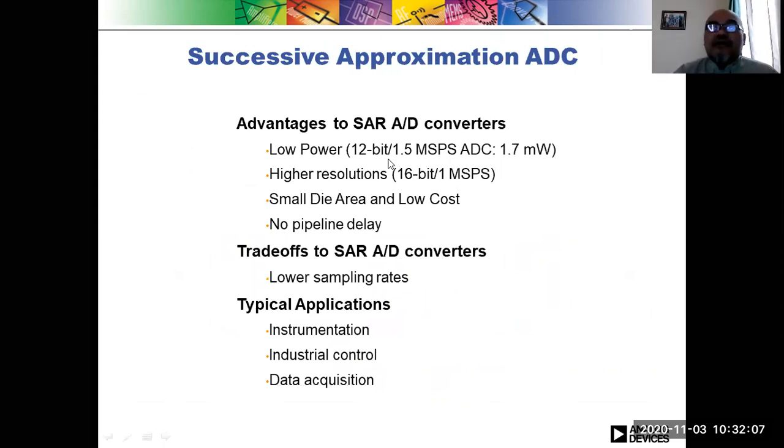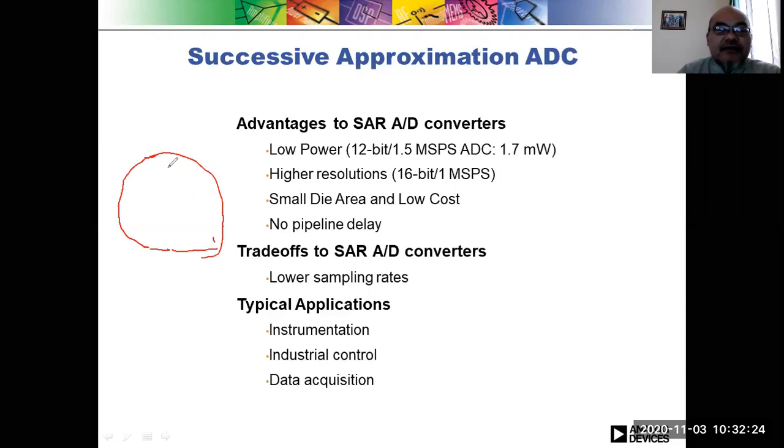Yeah, so you know that in microelectronic fabrication you have a wafer area. Maybe I have discussed this in the sensor class. This is usually in microelectronics IC fabrication. The diameter is either 4 inch, or 10 centimeter. Usually this is used in research, but in industry they usually use larger, up to 8 inch, about 20 centimeter, and sometimes 12 inch, about 30 centimeter.